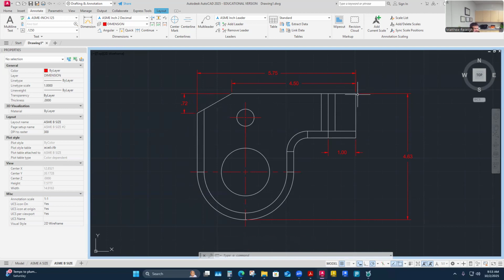Then that means if I just have a line and I define that, and then I define that and come down from being perpendicular to that point, it'll actually lock in. This is a little triangle essentially that I kind of built. And this is the hypotenuse where my part actually is. With these three dimensions, I should be able to lock in its size and location.